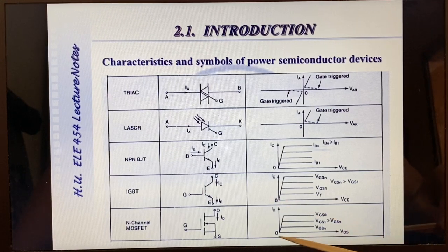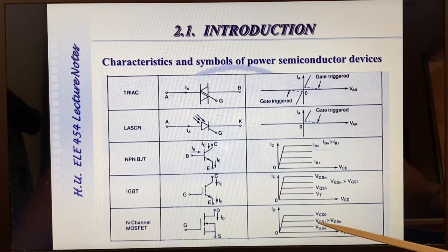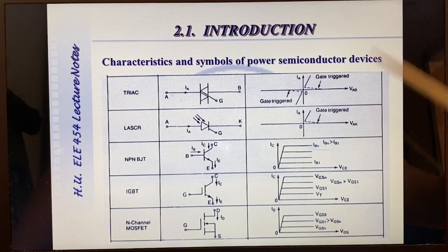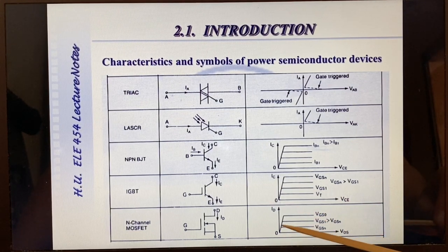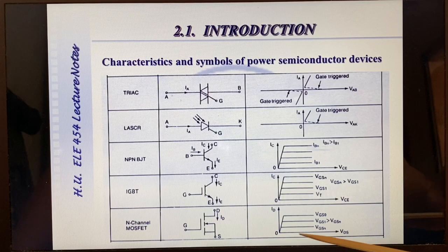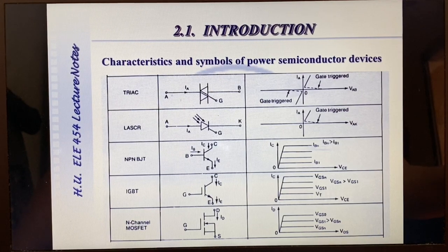The drain current against drain to source voltage with gate to source voltage as a parameter is seen here. So here again, the operating region is the constant resistance region here during on state, and during off state for VGS equals 0 or negative values, the drain current is very small, negligibly small.